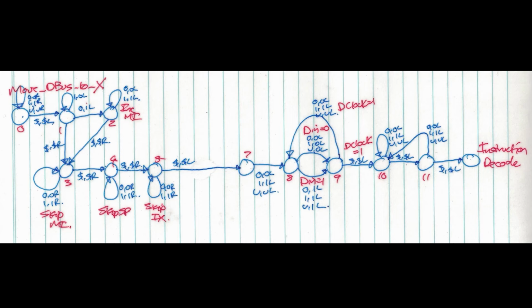I hand-designed the small state machines that make up the overall 6502 state machine, and they all ended up resembling microinstructions. This particular one is from a slightly different version of the machine, but it copies the data from the data bus register into the X register variable.